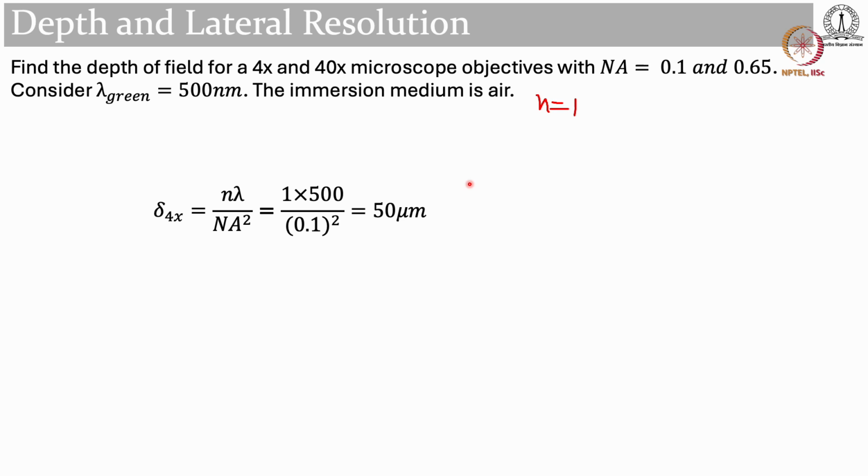If the flow you want to visualize is much larger, say over 200 microns, then this 50 micron should be sufficient for you. However, in microfluidics we normally work with much smaller depths, so 50 micron gives you a depth averaged velocity field and not an in plane velocity field.